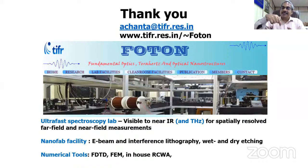Now there are these laser scribes, with a two-photon polymerization based technique where you can get really sub-micron features by laser exposure. You can either move the stage or move the beam to write whichever patterns you want from the software directly. No mask is needed for this. Yes, there are several techniques which don't require very high-end, costly equipment, or clean room and other resources.